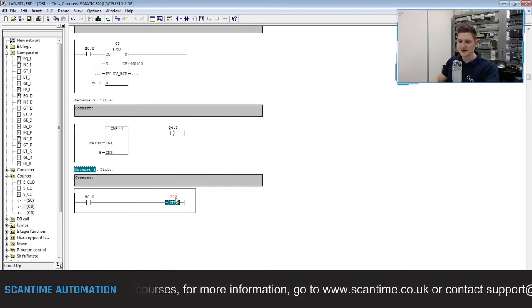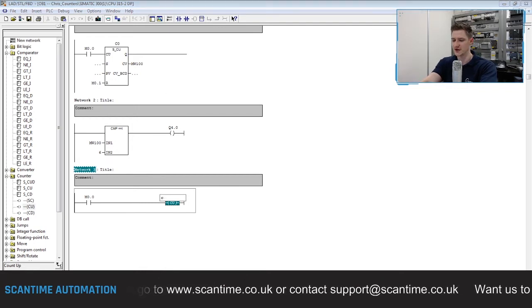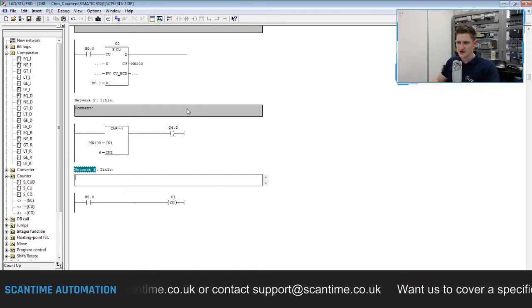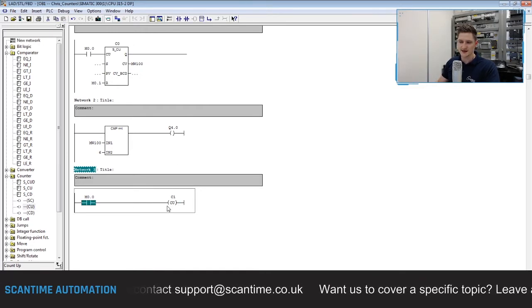So here we've got an inline instruction, and it's asking you for the counter number. So here we give ours C0. We can't use C0 again, so we'll use C1. And there we go. So all this does is when M0.0 turns on, it counts up the value inside of C1.